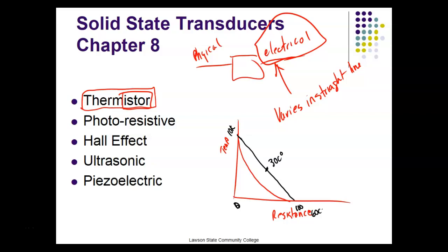You understand? So what we want to do is we never want to operate a thermistor over its entire range, because it would be what? Nonlinear. But if we come over here and operate it between a very small range like that, it appears to be linear, right? You understand that? So this is the way it works in your air conditioners, in your HVAC. So if you've got a digital thermometer, guys, how does it sense? What does it use? It uses a thermistor, right?